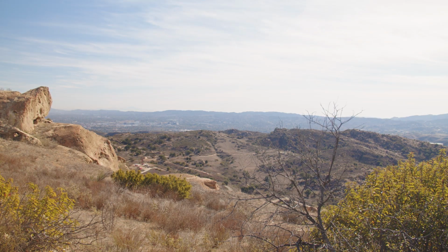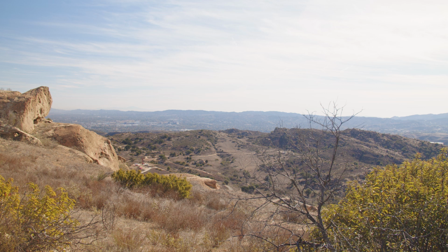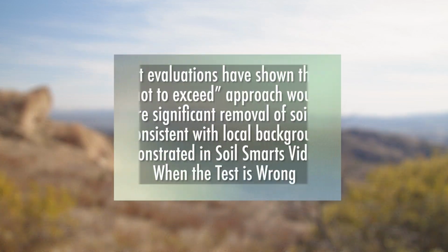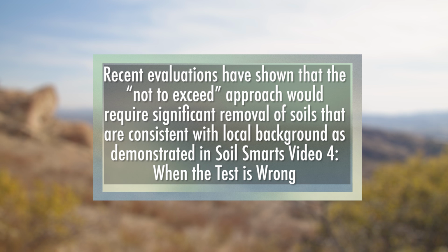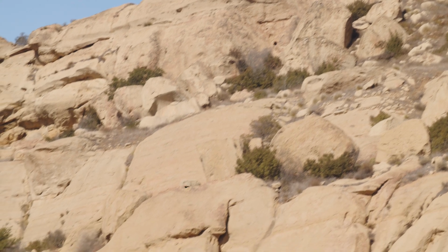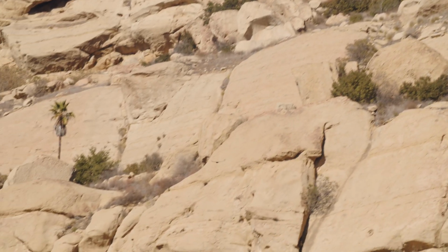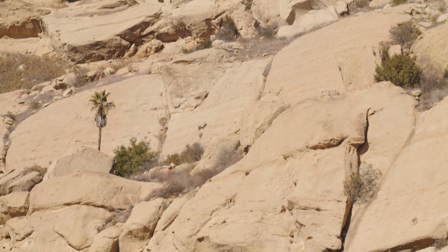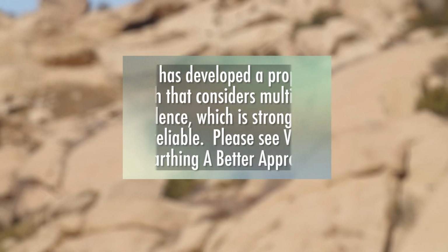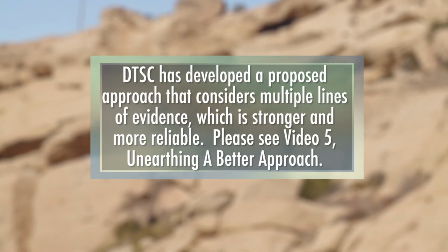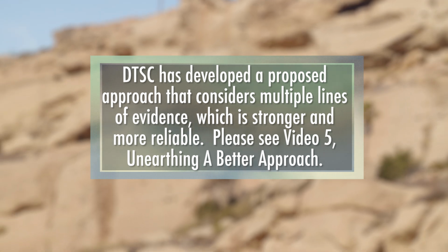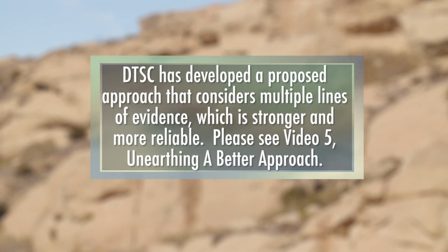Also, recent evaluations have shown that the not-to-exceed approach would require significant removal of soils that are consistent with local background, as demonstrated in the Soil Smarts video number 4, When the Test Is Wrong. DTSC has determined that the not-to-exceed approach does not accurately evaluate when concentrations in soil are consistent with local background. DTSC has developed a proposed approach that considers multiple lines of evidence, which is stronger and more reliable.